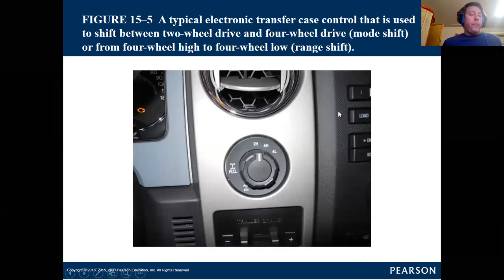All right, so how do we control four-wheel drive units? There are two ways manufacturers allow the driver to have control over the four-wheel drive engagement, and this is typically on your part-time four-wheel drive. Your all-time four-wheel drive vehicles are just all-time. They sometimes give you the option for low, or a traction control button that's part of the four-wheel drive system, where they'll have you primarily in an 80-20 split of power, and then if you click into a traction control mode, it might split it more uniformly, like 50-50.